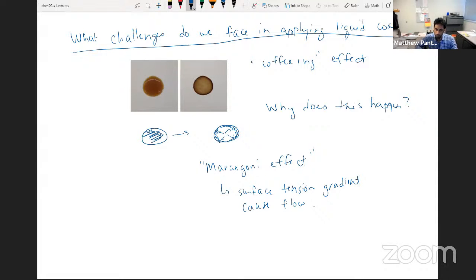If you have a higher surface tension at any point, there will be flow from low surface tension to high surface tension. We used that phenomenon to explain the stability of soap films that you would use to make bubbles, and that applies to bubbles themselves. If you made a soap bubble, why are you able to touch it, for example, without it bursting instantaneously, or why is it even stable to begin with?